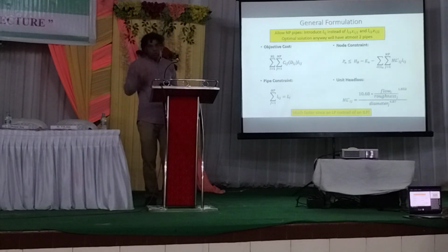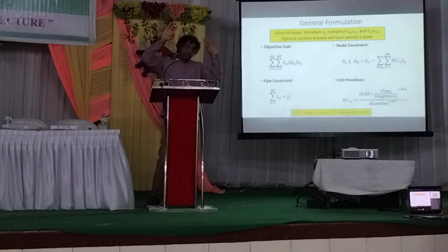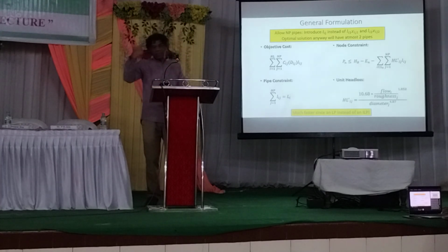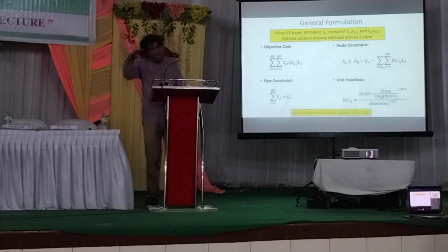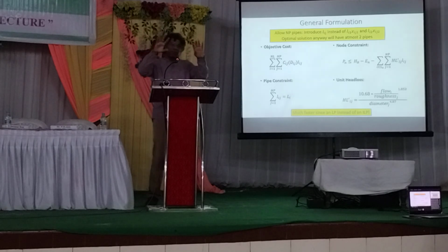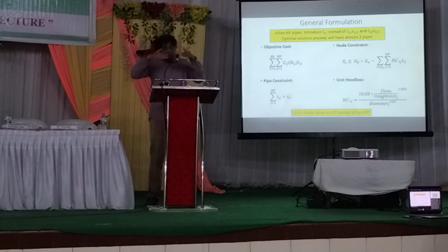You say, why worry about 2 links? We will say, you can use all possible 100 diameters. We are not going to say use only 2 diameters. Now, mathematically we know that the best network will have only 2 diameters. What it means is the other 98 will have 0 length. But we will say for all 100, please tell us the length. So it actually simplifies the problem.